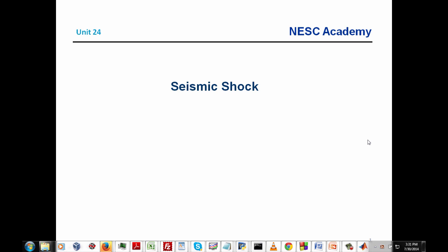Today we're going to be continuing with shock, and we're going to be talking about seismic shock. An important point I want to make right off the bat is that some of you, for example, deal with pyrotechnic shock, and we will be covering that in the next webinar after this one. But really, the principles that we're going to learn today apply just as well to pyrotechnic shock as they do to seismic shock. The big difference being that pyrotechnic shock is a high-frequency event, whereas with seismic shock, the energy occurs at very low frequencies.